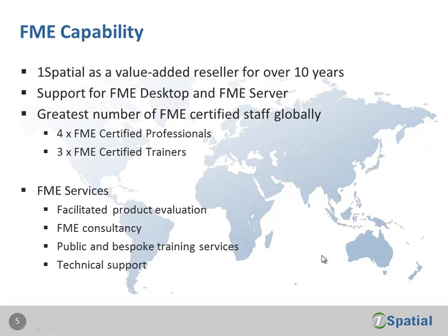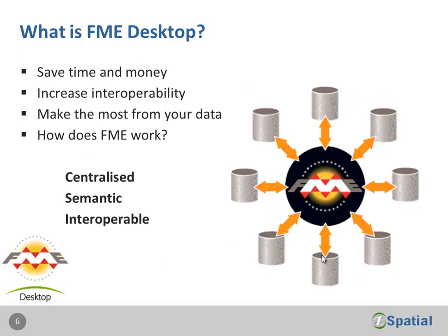The focus really is going to be on FME Desktop though for this session, and often brand new users are not quite sure what the product does, although it's very immediately obvious from some of the marketing that surrounds the product that highlights that it is a data translation tool. But really the power that lies in FME is with the engine. So FME can process data from a MapInfo tab format and write it to an AutoCAD DWG, but FME also knows that DWG can write data out to GML, but GML cannot write to NTF.